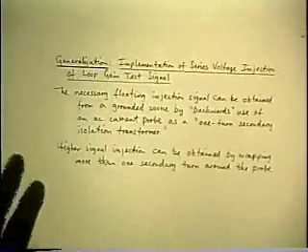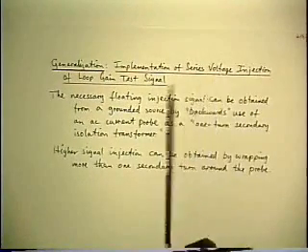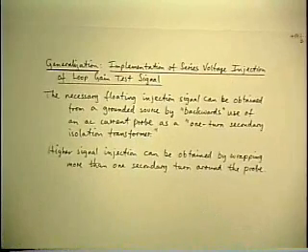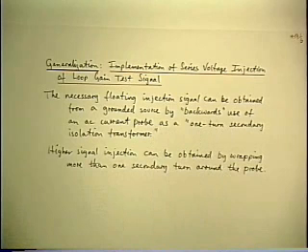Okay, so I've used that example as a vehicle to show a number of things. In particular, the implementation of how you get a series voltage injection to make a loop gain test signal. And you can use an AC current probe backwards as a one-turn secondary isolation transformer. A word of caution that I'm sure isn't necessary here: don't use a DC clip-on current probe, because it ain't a transformer. It's a Hall effect device. Hall effect devices don't work backwards like this.